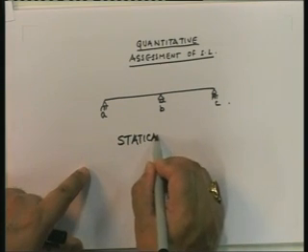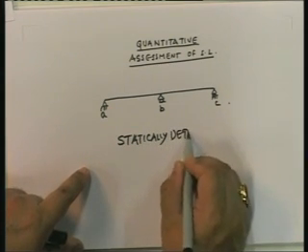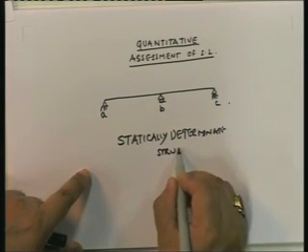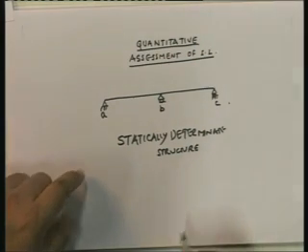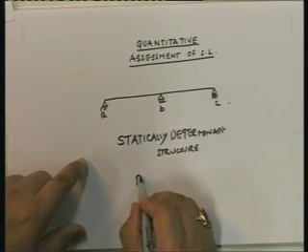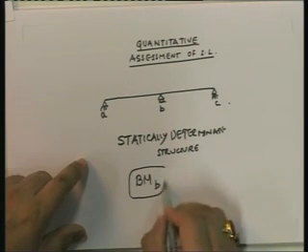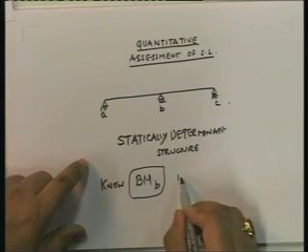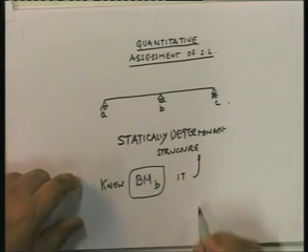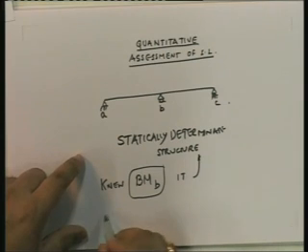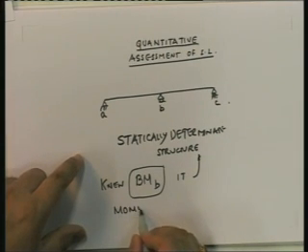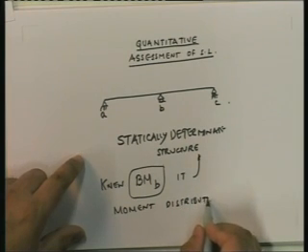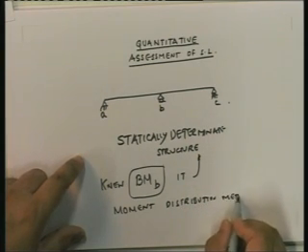So therefore, what we do actually is, see, the whole thing over here is to make it a statically determinate structure. And we know here that if we knew the bending moment at B, it would be a statically determinate structure. So we use the moment distribution method.